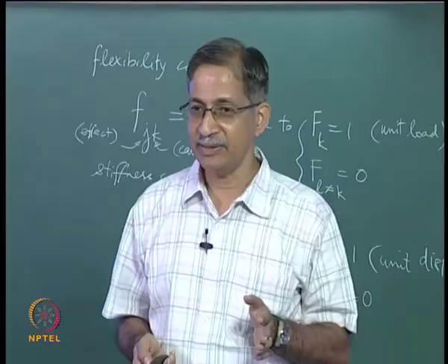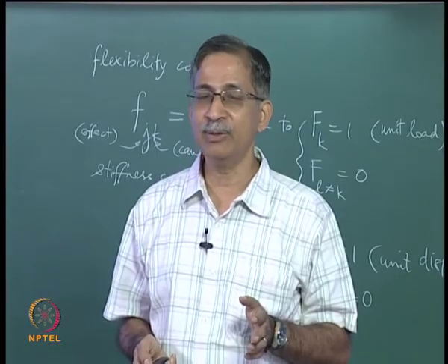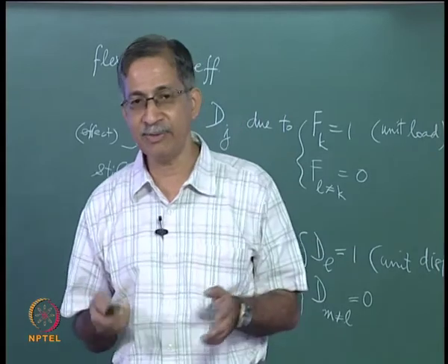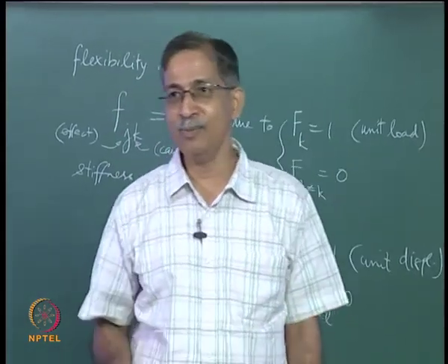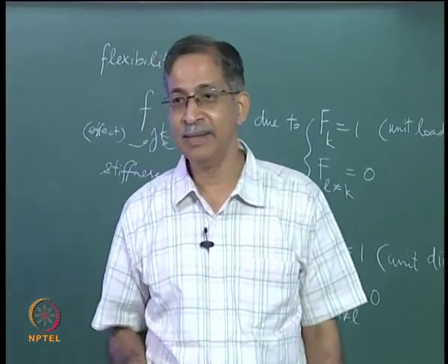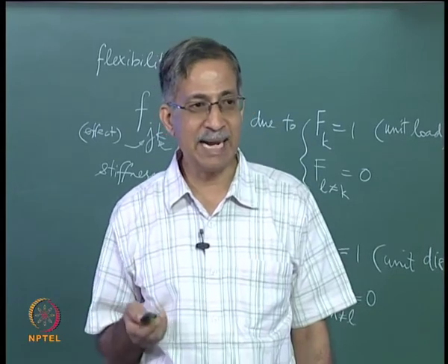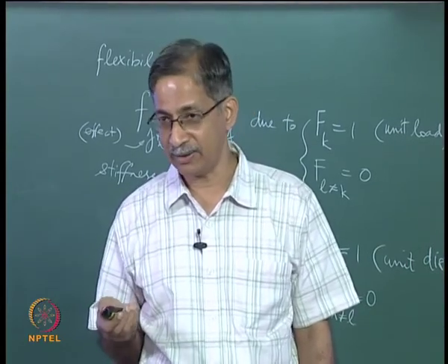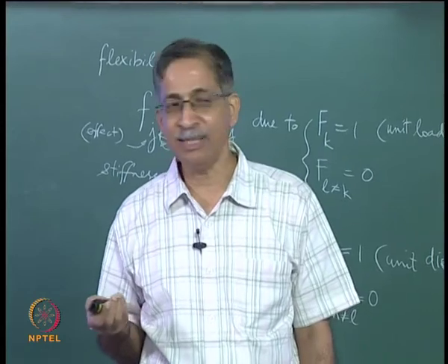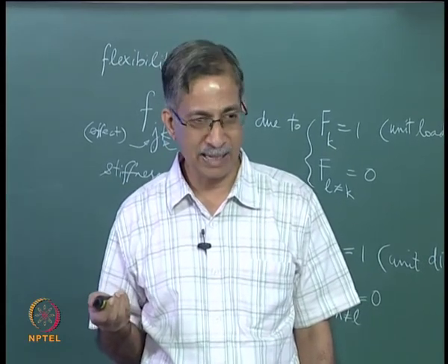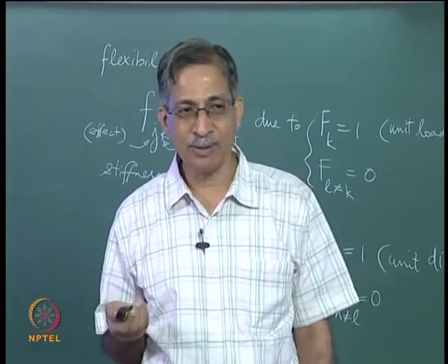So what will you do? You apply a force. What we have here is a real displacement field. If you divide M by EI, you have got the curvature diagram. What you need to do is a virtual force. This is what you should do, this is what everybody does, but there is a problem with this. The problem is you again are dealing with a statically indeterminate structure, and you need to spend some time to figure out the small m diagram for this. Is there a way out which is easier?